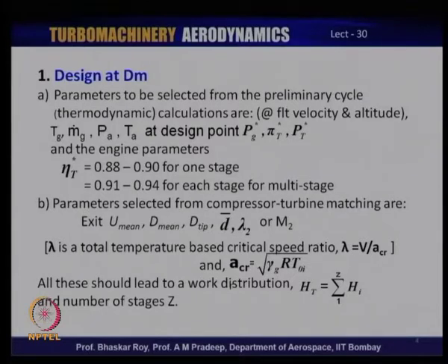combustion chamber delivery temperature T G or T 03 or whatever we have talked about in terms of cycle. In terms of axial flow turbine, it is T G, which is T gas at the entry to the multi-stage turbine, and that is coming from combustion chamber. And then of course, we need to know what is the mass flow inclusive of the fuel that has been burned, and that m dot g is the mass flow that is coming from combustion chamber. And then of course, the pressure that is being supplied from combustion chamber, pressurization that has occurred in an axial flow compressor or any other kind of compressor, and that pressured gas is also carrying a very high pressure that is to be supplied to the turbine.